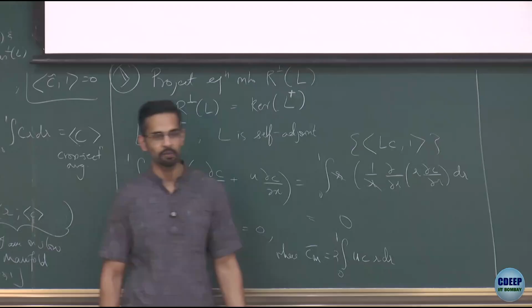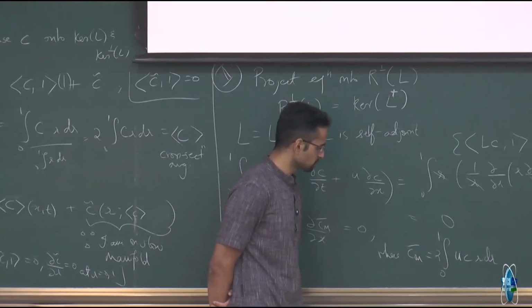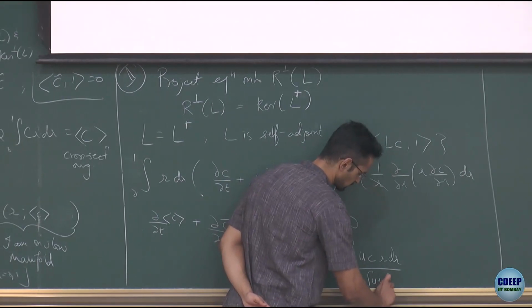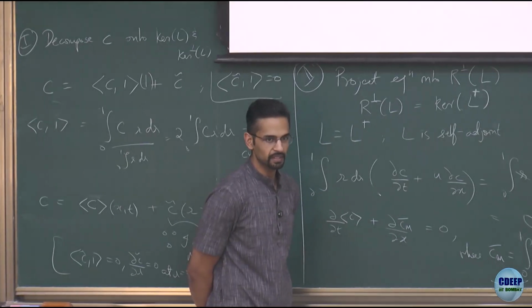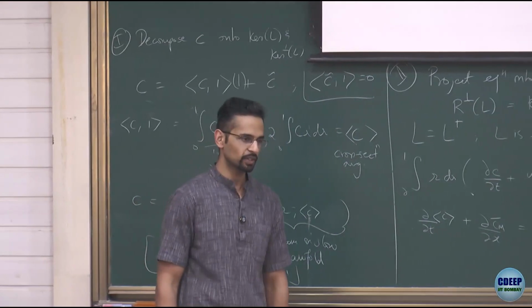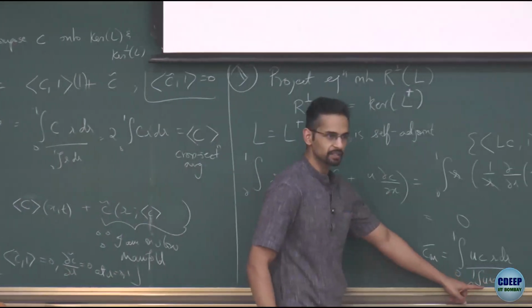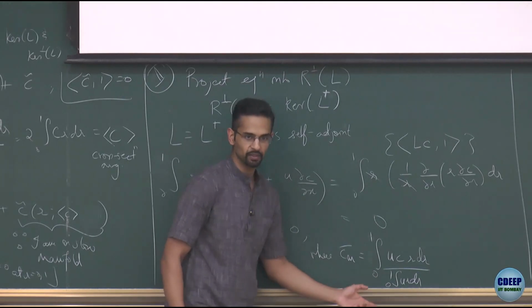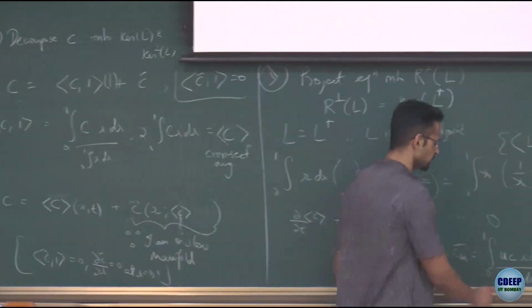So it's like taking the total flow rate of material dividing by the area. So actually I should be more careful. Then it makes sense. Otherwise, it's not a concentration. So I've taken the total mass of the species divided by the flow rate of the fluid. But you see, what is this? This is nothing but the mean concentration, okay, which is scaled in my problem to 1. Correct? That's why it will not appear in my calculation. This is nothing but U average, but because I scaled U by U average, this denominator becomes 1, right, in my scaled problem. So in my scaled problem, I'll just get this.